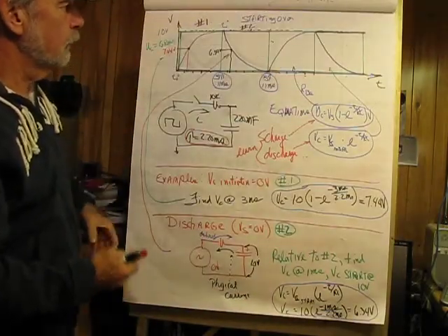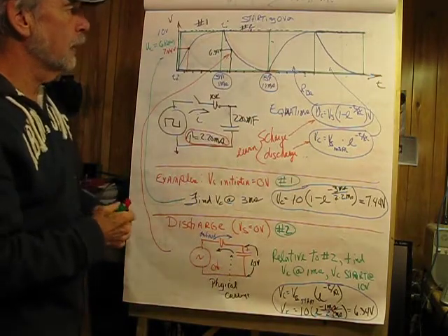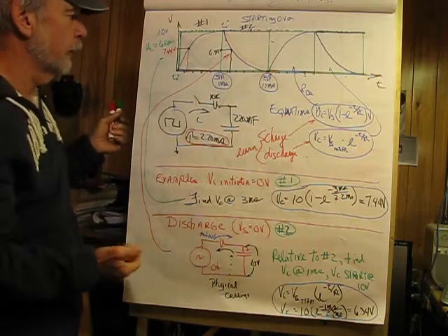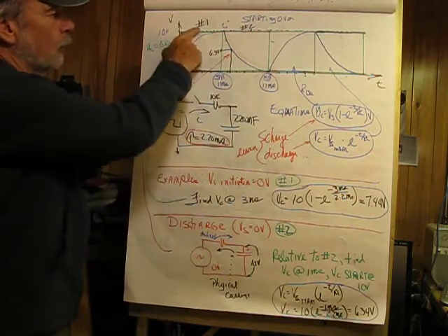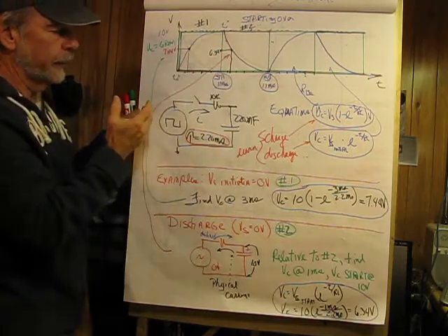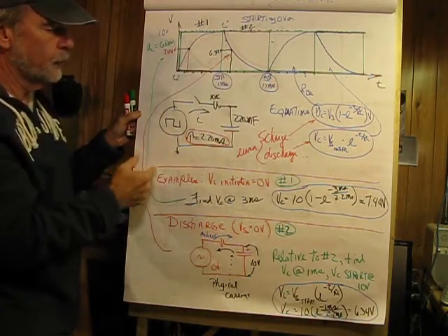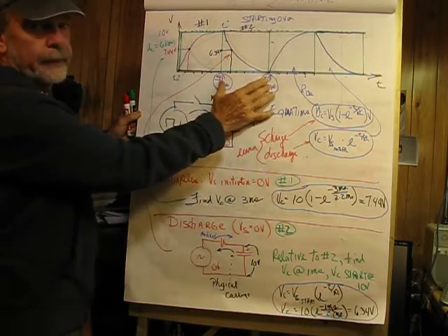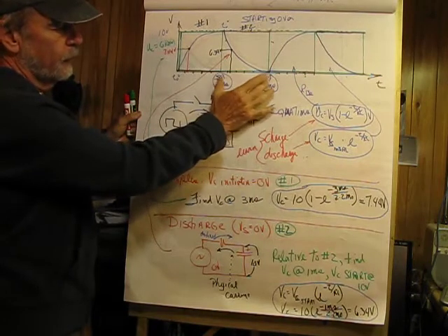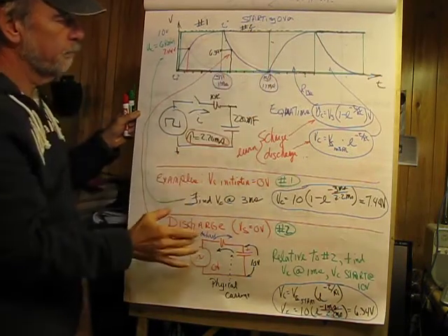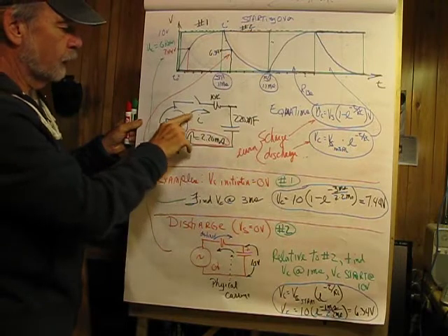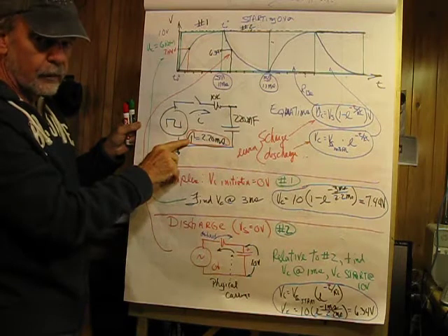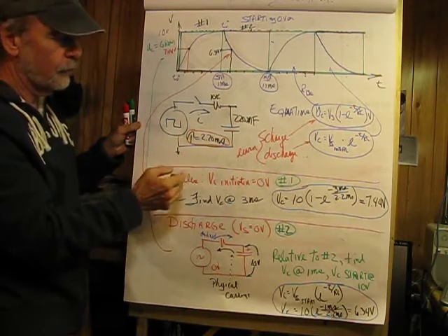Now this page, again, we're starting with 0 volts on the capacitor, and this may look pretty bad, and there's a lot of writing here, but this is going to be number 1 and this is going to be number 2, and when we do the calculations we'll be referring to each. 5 tau equals 11 milliseconds, and then I'm starting over again, so instead of this being 22 milliseconds, it's 5 milliseconds for this piece. I'm defining the current flow in this second, and tau, the time constant, R times C, is equal to 2.2 milliseconds.